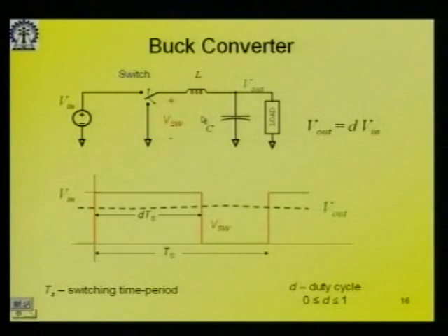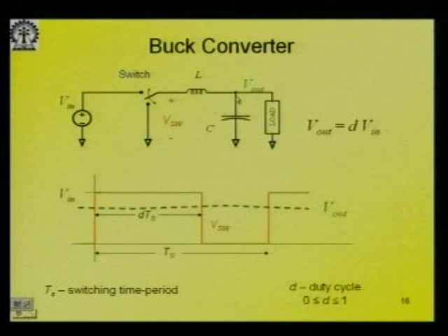The current will rise linearly in the first part, where the input voltage is greater than the output voltage. In the second part of the waveform, this point is grounded, so the current through the inductor will go down, and the inductor will be discharged.